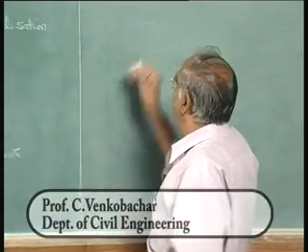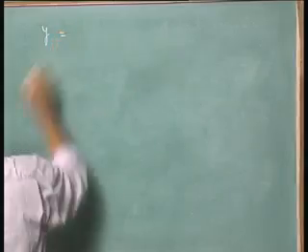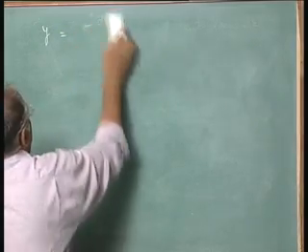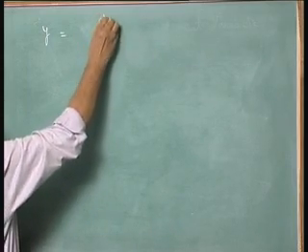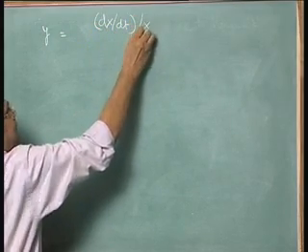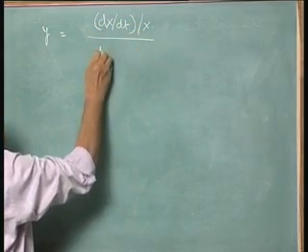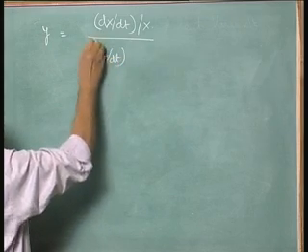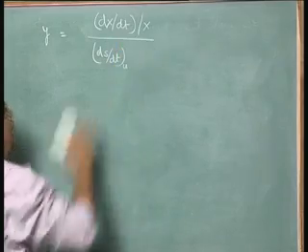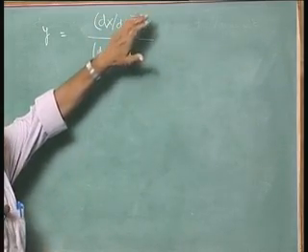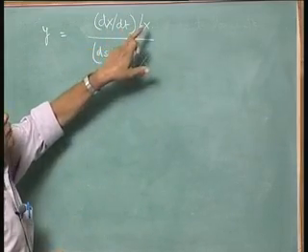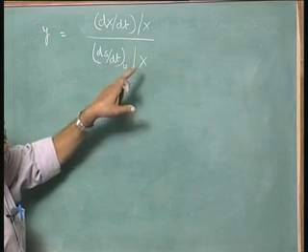So the yield coefficient is given by Y is equal to minus dS by dt, sorry, let me write it clearly, Y is equal to dX by dt over X divided by dS by dt utilized. So I will divide both the numerator and denominator by X, dX by dt over X, dS by dt utilized over X.